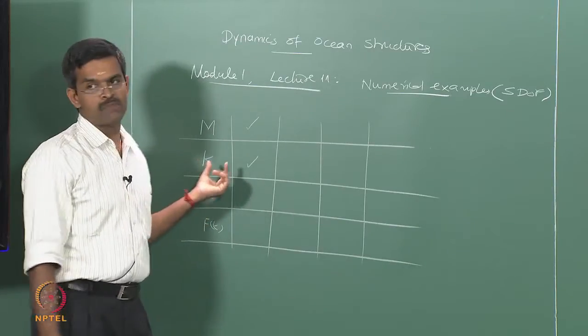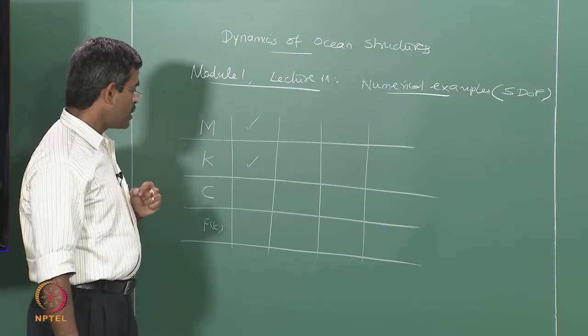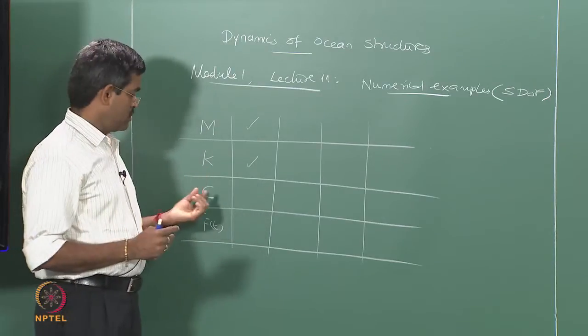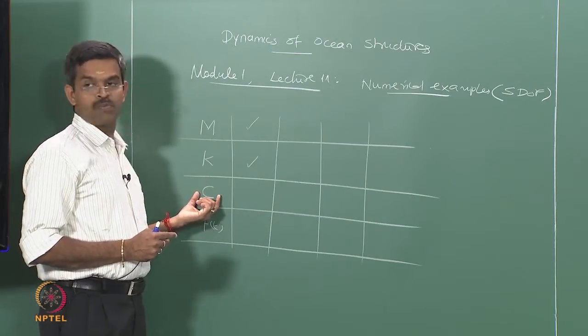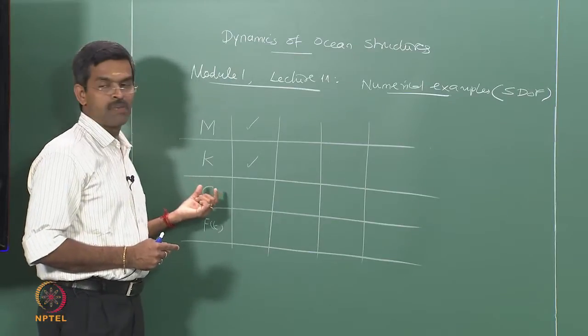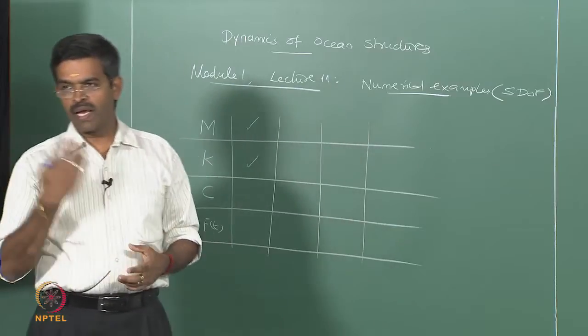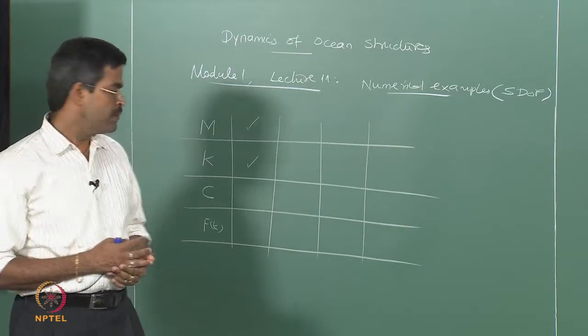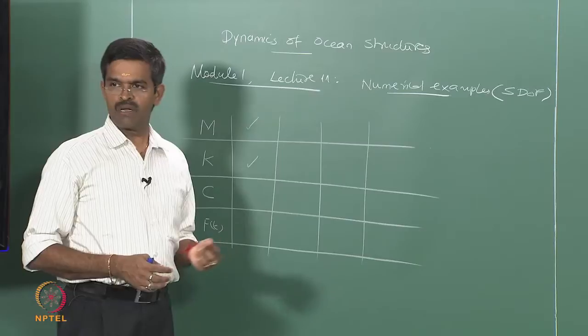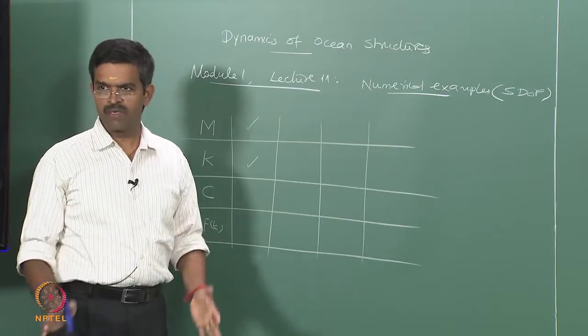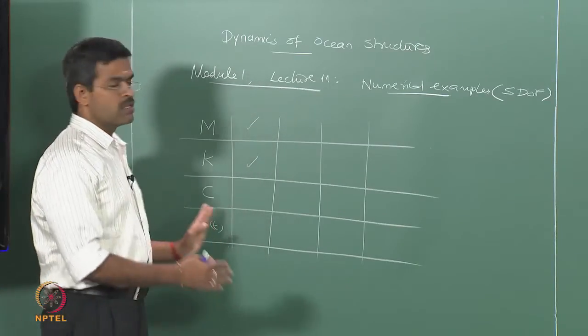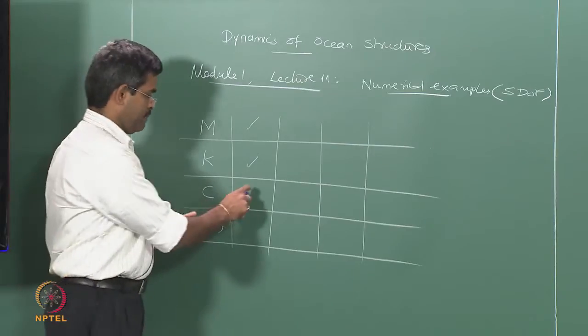So, K will always be present in the system. Now, one can always ignore the dissipation of energy or the response because of damping. The damping is always present by two external sources. One can be aerodynamic, the presence of air will also cause damping. The second could be hydrodynamic, which is obviously and inadvertently present in offshore systems, but for hypothetical consideration we can neglect them.